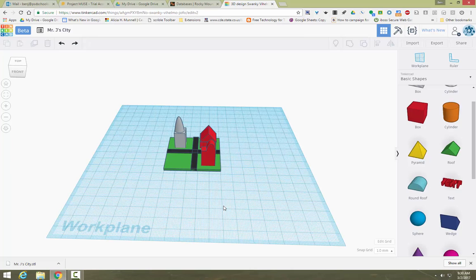Before we print, I'll double check the file and make sure that everything is going to print okay. If you have overhangs or things like that, you're trying to print in midair, of course that won't work. So the main thing is to make sure that if you add like a roof to one of your buildings, that it's not hanging over, because you can't print plastic in midair. It has to have something underneath it. So I guess don't get too crazy with your designs, but as long as there's something supporting underneath, then you can basically draw whatever you can imagine.